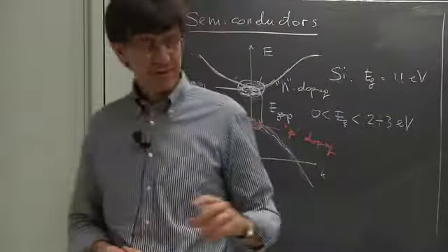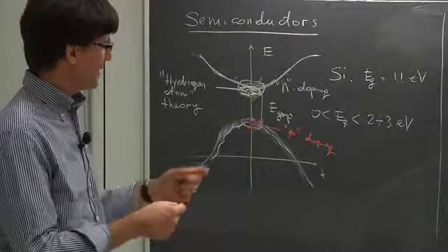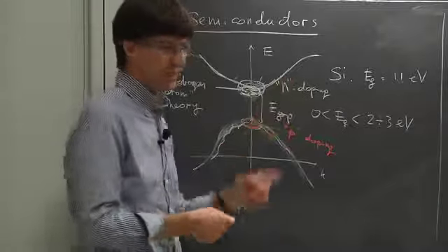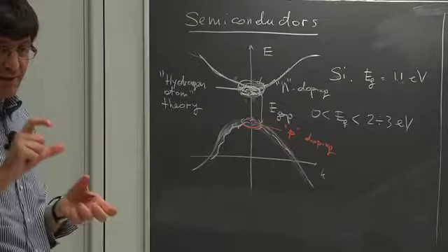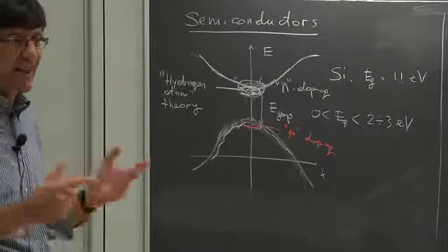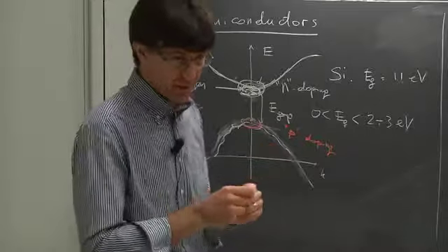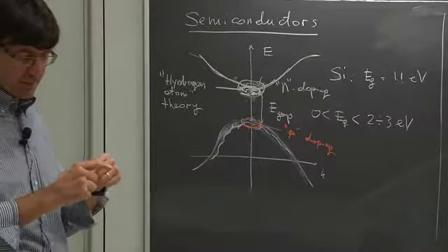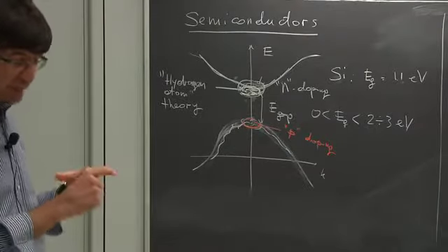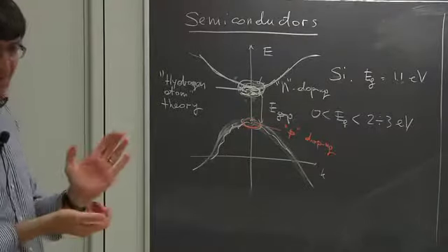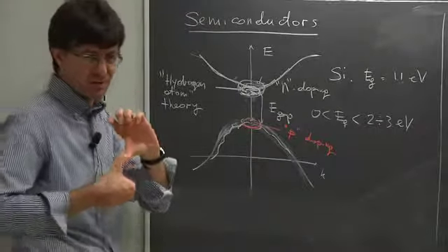With semiconductors, you can take silicon and put together a piece of silicon with N doping and a piece of silicon with P doping. They will have the same lattice spacing, so they can be grown together. A standard diode in any electronic circuit is made of two silicon pieces with different dopings, N and P. Okay? And the two of them are mechanically very stable. They're attached because they are essentially the same kind of crystal.